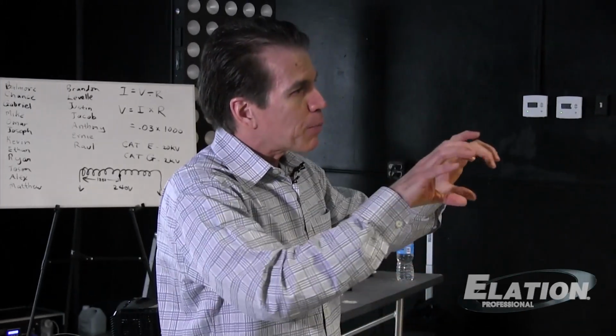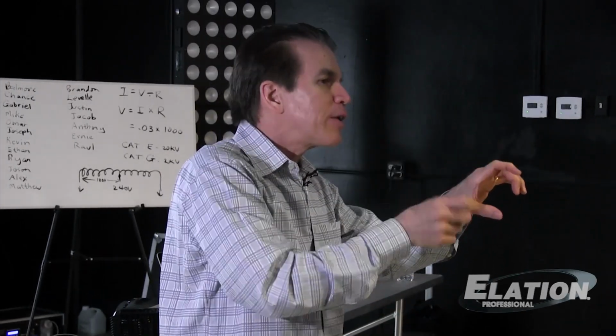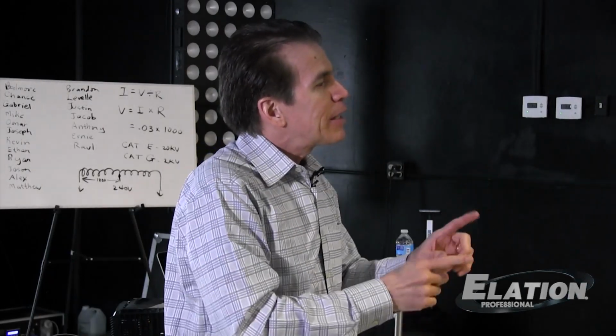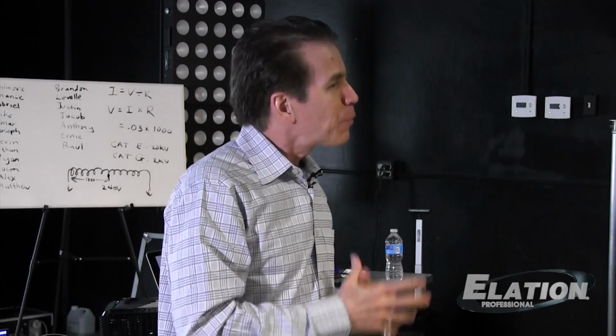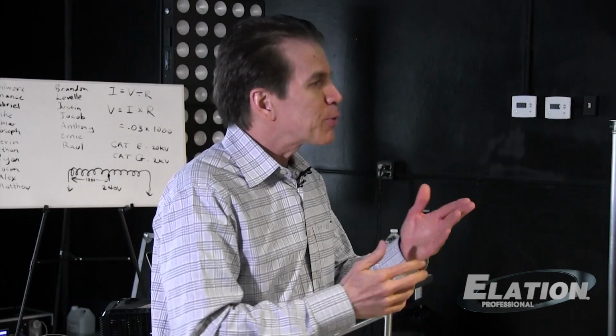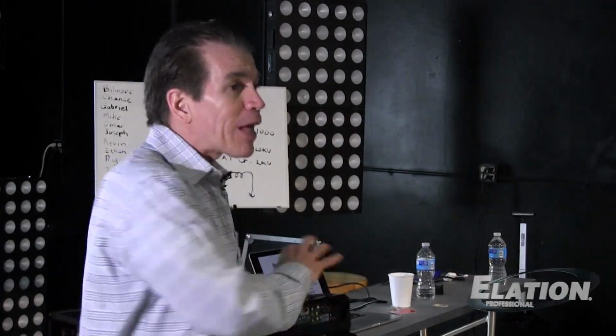So that when you've got the plastic PVC, then you put the clamp on it, you tighten it down, it prevents that bolt from digging into the truss and marring it, right? But it also isolates that truss from that piece of metal. So it doesn't bond it to the electrical system. So if you do that with all your lights, then your truss is not bonded.